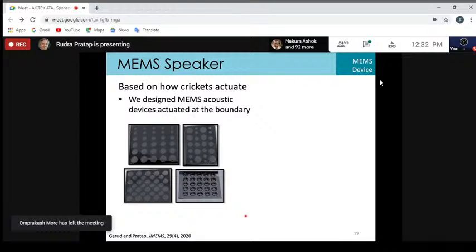All the normal speakers that you have seen so far, all these electromagnetic speakers that we use, they all have a coil in the center. A magnetic coil, and that's what pushes a membrane attached to the coil up and down when you send current through the coil, and that's what produces the sound.